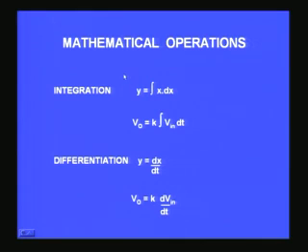You also have another mathematical operation, which is much more complex, which is called integration. You can perform an integration. Y is equal to the integral of x dx or x dt, depending upon whether you are integrating with reference to time or the space variable. So here, if I have a circuit where the output voltage is k times the integral of V in dt, V in is the voltage input. So it is an integral of the input voltage which is related to the output voltage by a factor k. Then this circuit performs integration of the input voltage. The output is an integral of the input.